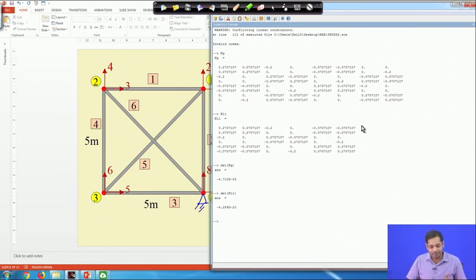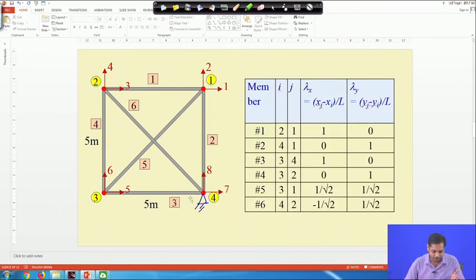It is very obvious. You look at this structure. If we have a truss like this and support only at this point with a hinge, is the structure stable? This structure is not stable because we have not provided the number of constraints required to stabilize it. That is why the structure is not stable, and this will be manifested in the solution. When you run this code, you will see that there is something wrong in the structure. That is the reason why you could not solve this structure.